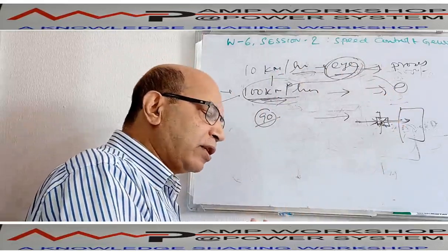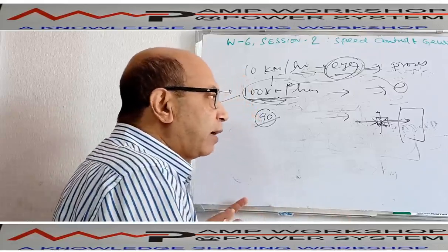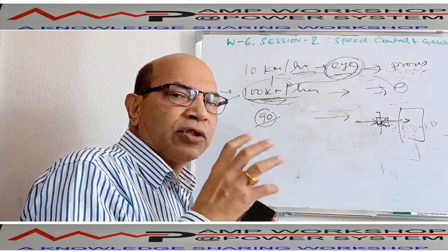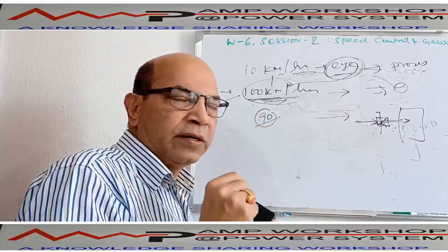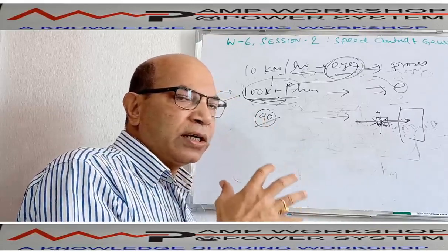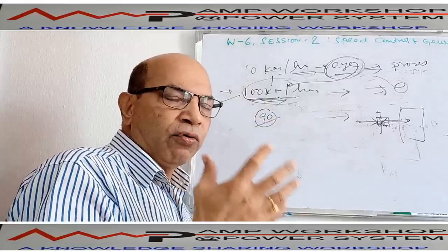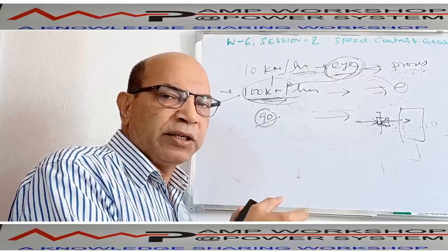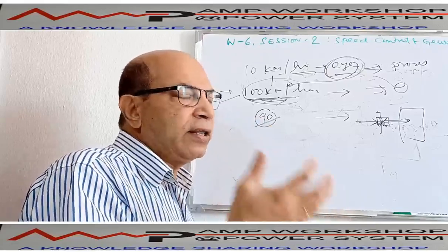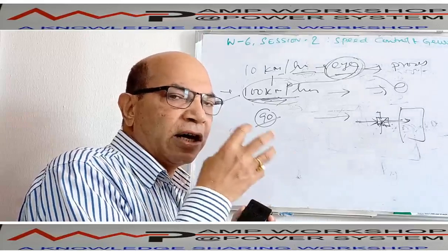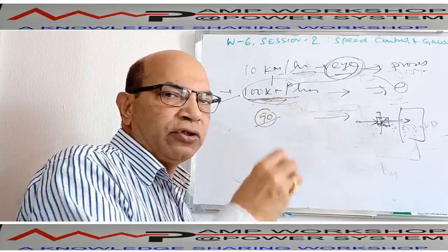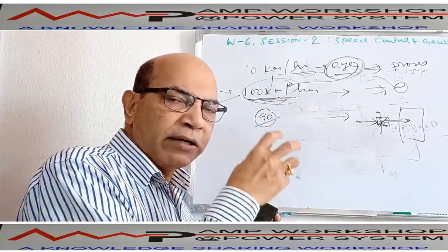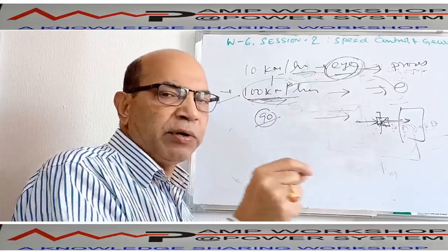Here in the case of a turbo generator set, it works the same way. In the turbo generator it is the same thing. We have to sense the present speed of the turbo generator set, or the present frequency of the generator. Then this turbo generator's control element has a brain or processor where the required speed is already set. Suppose 3000 RPM for a 2-pole machine, 3000 RPM speed is required, or 50 Hz frequency is required, that is already put there. So there will be a sensor which will sense the actual frequency or speed, and the processor, like a brain, will compare the actual speed with the set speed.